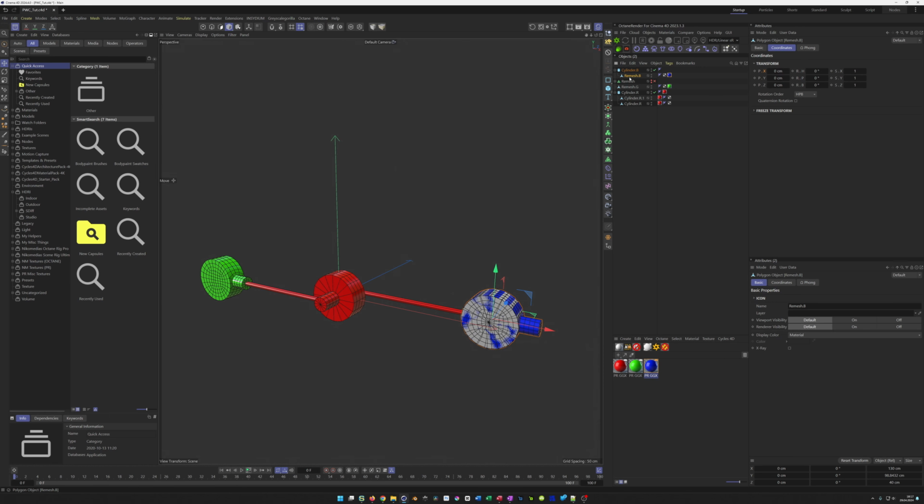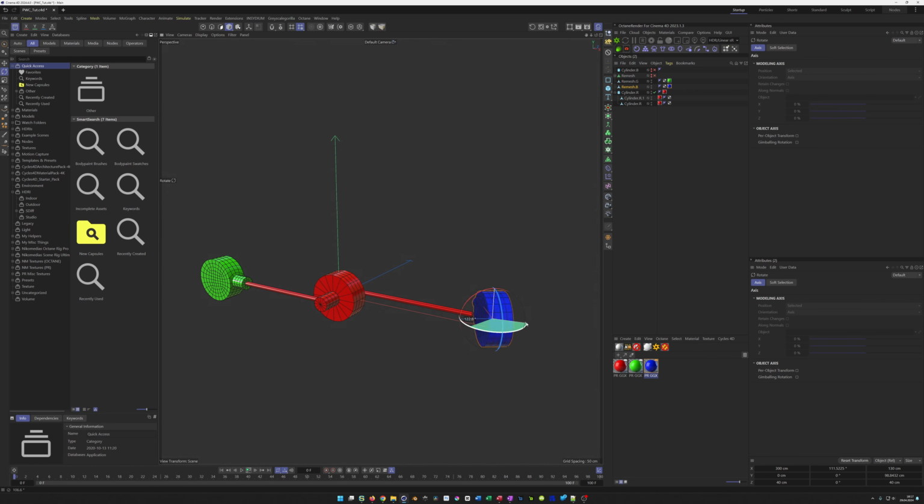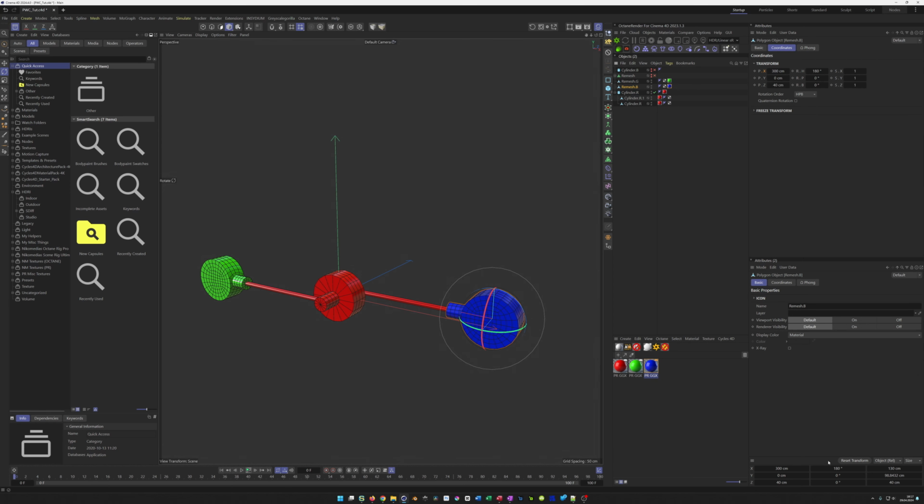So that means I can bring this out again. I can hide this, we don't need it. See, the only thing is we have it in the wrong direction, but this is no problem. After rotation, rotate it 90 degrees, 180 degrees here. Done. But I want the axis at 0, so I go to the B. You see the axis here is at 180. So I go in axis mode. This shortcut is L, or you use here the axis mode and simply bring it here to 0.